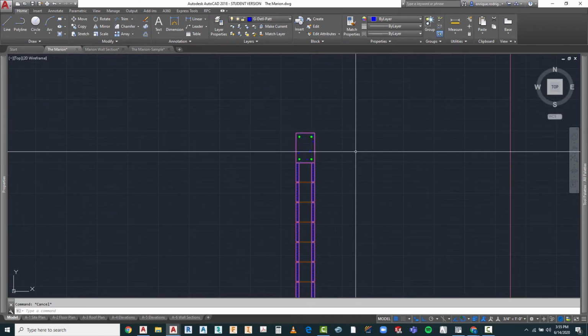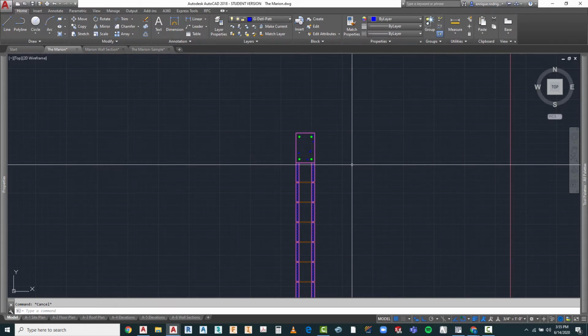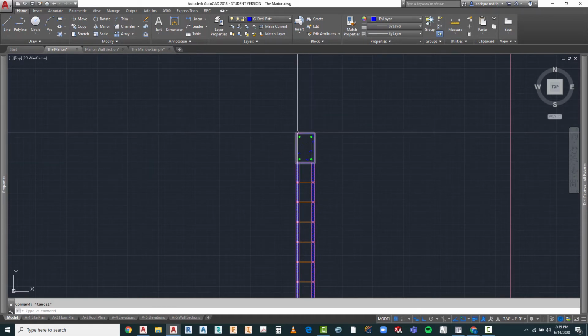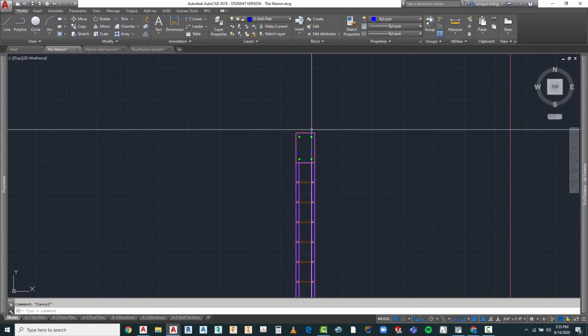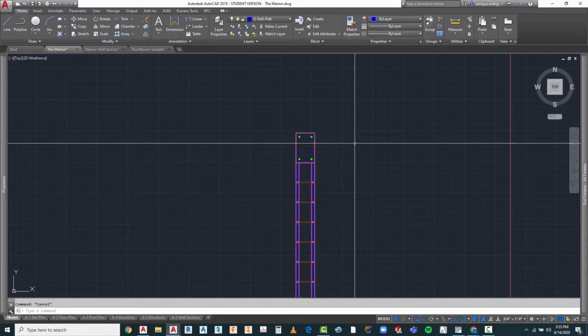The problem is that you'll get a chemical reaction that will begin to deteriorate the wood. So we want to create something that those rafters can rest on, and what we use is a wood top plate. The wood top plate undergoes what we call pressure treating, which is infused with a chemical under pressure and heat that then protects it from the reaction that you get between masonry or concrete and the wood.